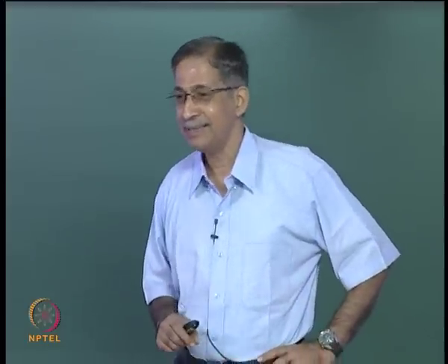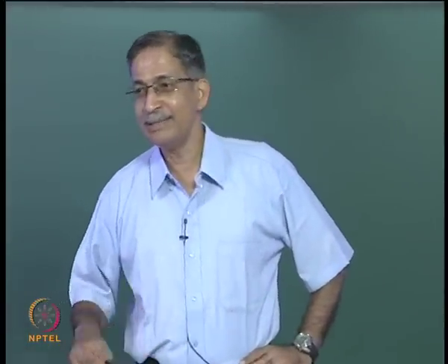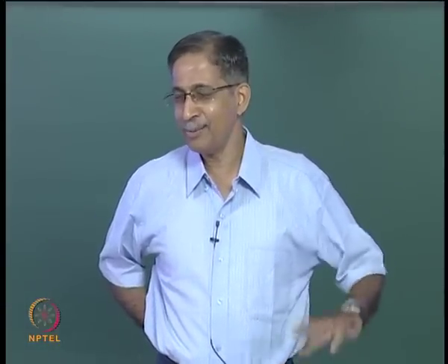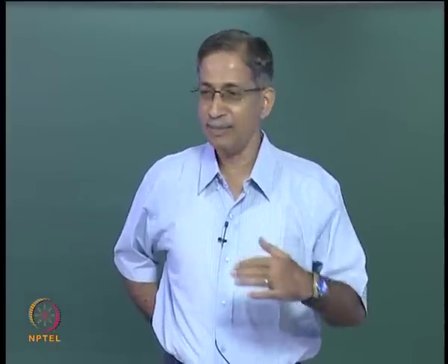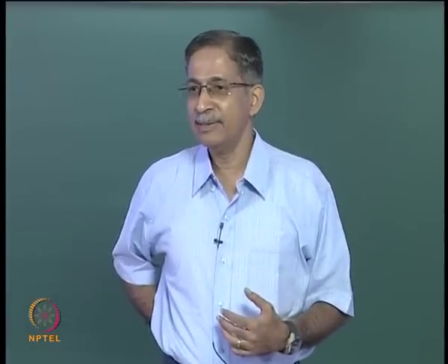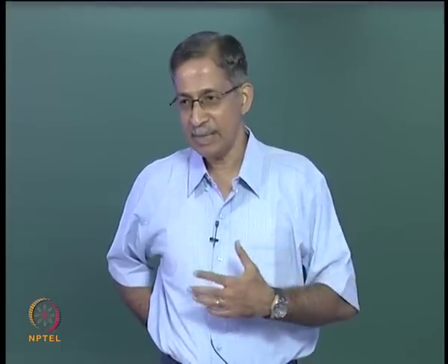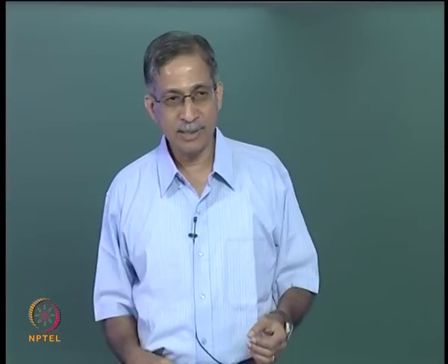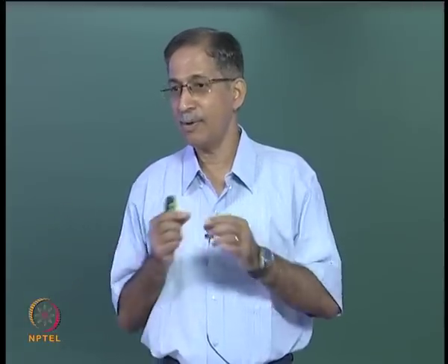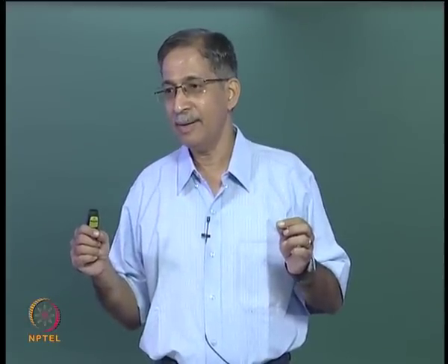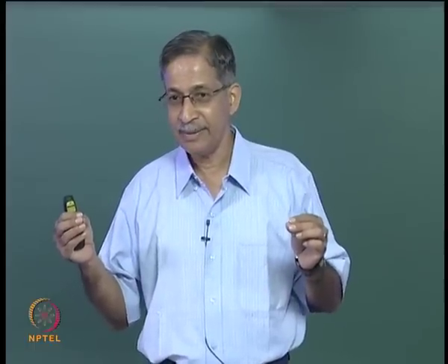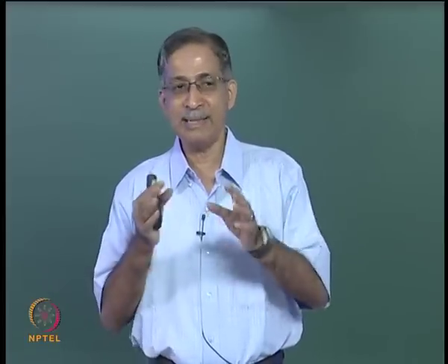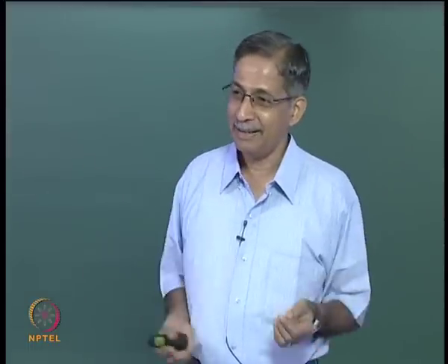The next question we now ask is, is that true or is it approximate? We are now digging a little deep into the subject. You will find that finite element analysis, which is something you will study in an advanced course, uses such displacement functions to develop the theory. You have a complicated structure, you break it up into small parts, they are called finite elements, and you try to reduce your degrees of freedom to the movements at the ends of the element, and you have to interpolate to get the information within the element, and if you are lucky you have got an exact formulation, in which case you get an exact solution.